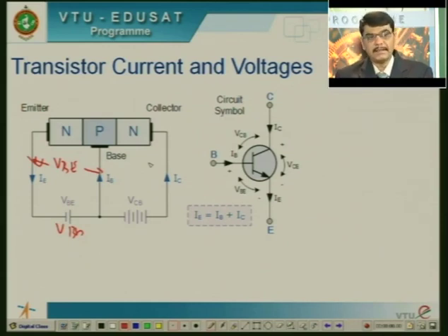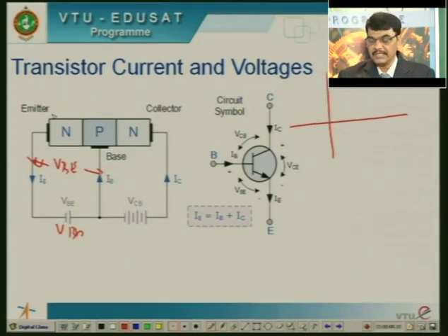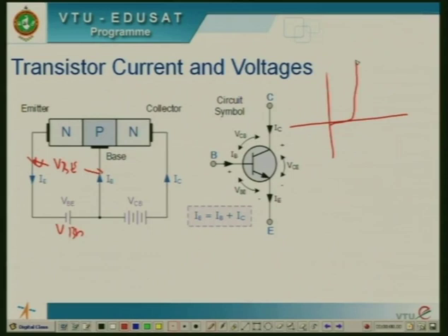This emitter current IE increases exponentially, because when this junction is forward biased it acts simply as a diode. The voltage across it stays almost at V gamma only, which is equal to VBE, the knee voltage of a diode. The base-collector junction is reverse biased, so whatever voltage is applied appears entirely across that junction, denoted VC.